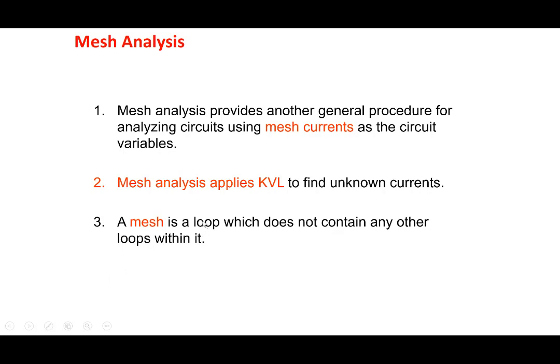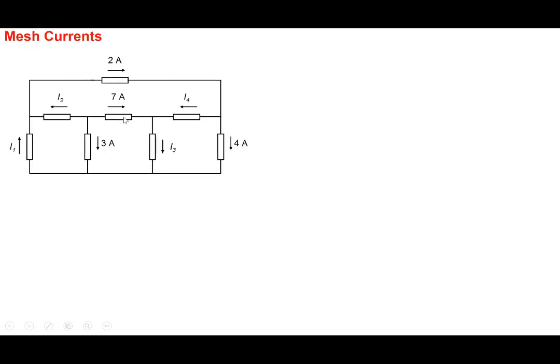All right. So let's say we have a circuit. If you recall, this was a problem in homework assignment number 1. Whatever these elements are, let's not bother. A mesh is a loop which does not contain any other loop within it. So look for these loops which, in simple terms, have nothing inside that particular loop. It's empty here. So look for these empty spaces.